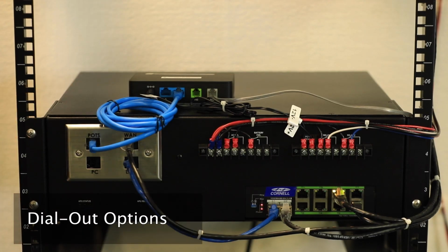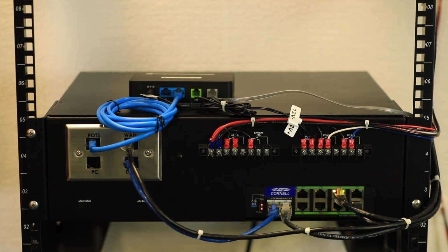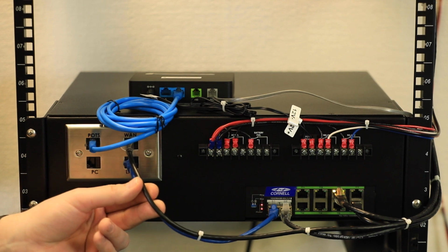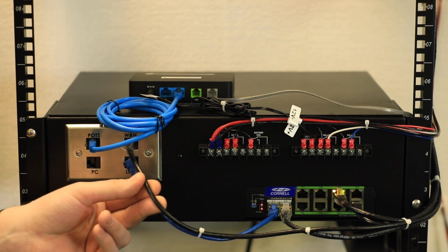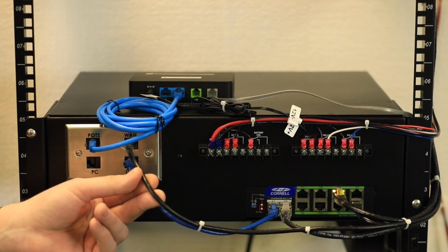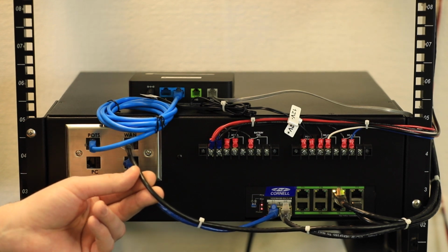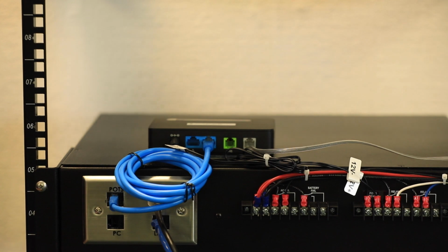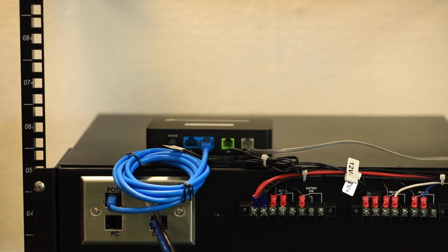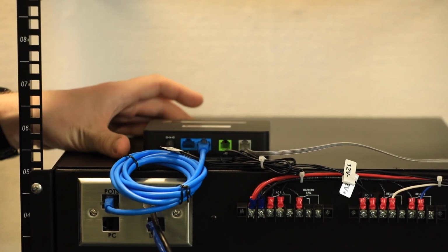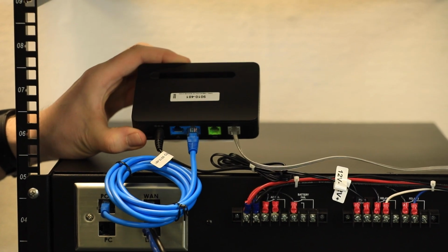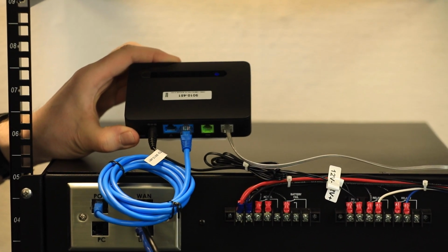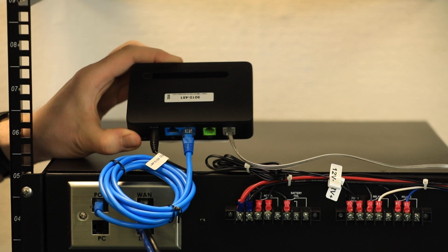Returning to the main head-end unit here, we're going to start talking about the dial-out options that the Sentinel AOR system has. Natively, it is capable of using a digital SIP type of phone line when dialing out. All you need to do is provide an internet line connection, as we went over before, to enable that option. Alternatively, the Sentinel AOR system can use an analog, or otherwise known as a POTS phone line. It's a typical RJ11 2-wire tip-and-ring telephone line to dial out.